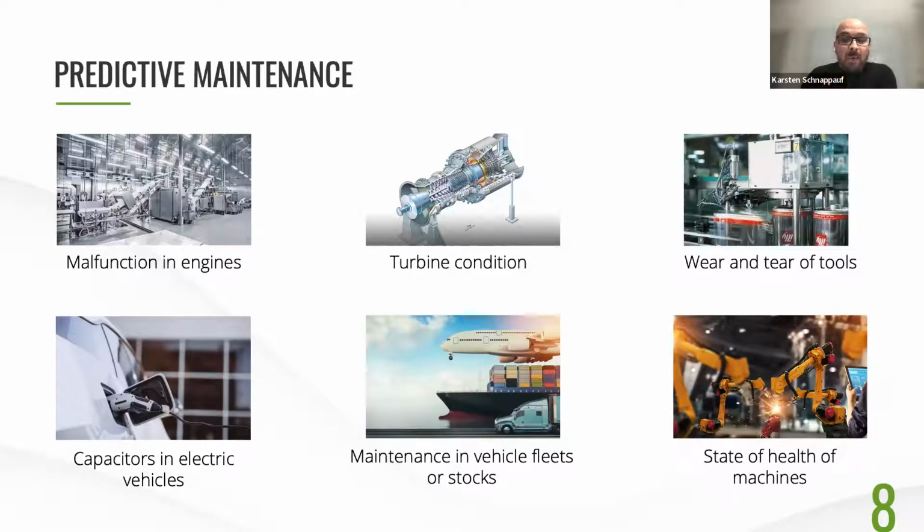And at this point, I would like to share with you an implemented predictive maintenance solution at our customer. The topic here was the early detection of the wear condition of a cutting knife of a packaging machine based on vibrations. Within 1 week, we integrated a sensor that delivers the time series of the vibrations, stores the data in a database, and we developed a high quality model with H2O that predicts reliably the degree of wear. And currently we are in the process of bringing this solution to production so that the end customer of our customer gains value from it with a better product at the end.